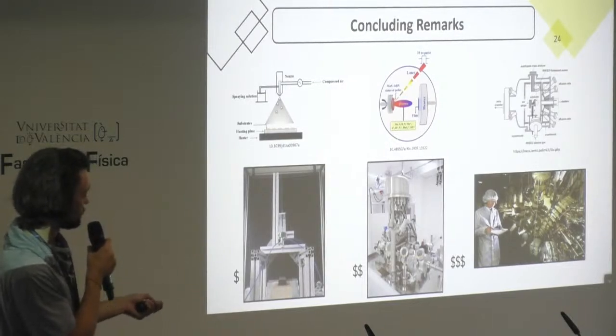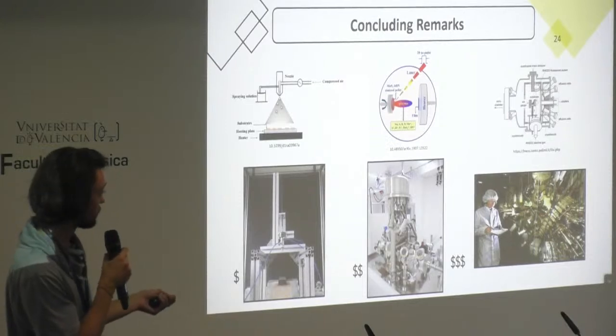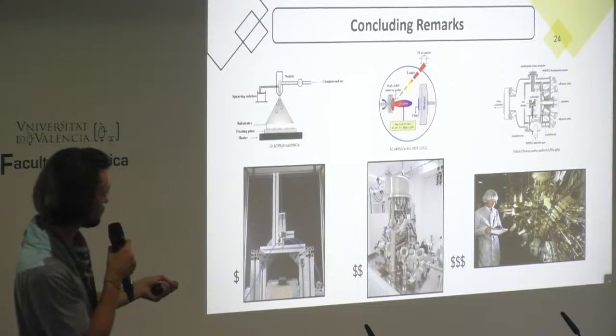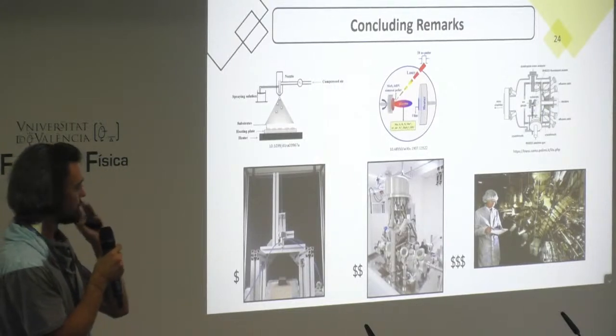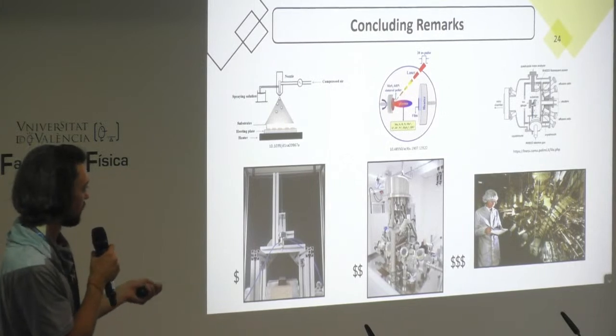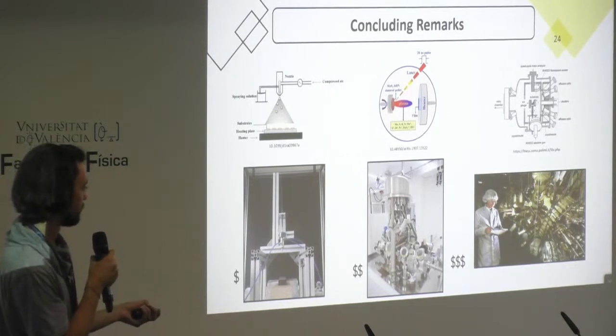And this is MBE, molecular beam epitaxy, and here what you directly have is some cells, some effusion cells, in which you can shoot beams of atoms, of pure atoms. So with this you have very high control of the material you grow.